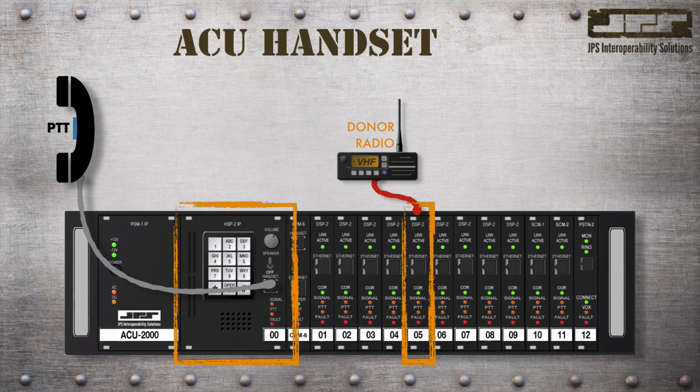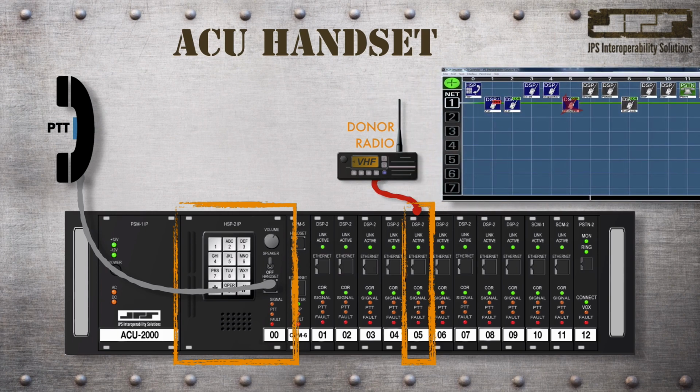At any time you experience communication issues associated with an interoperable cross-connection during actual operations, immediately disband the suspect interface from the interoperable cross-connection and then cross-connect the interface with the handset to conduct your troubleshooting activities. Do not under any circumstance begin troubleshooting with the suspect interface while in an interoperable cross-connection. By removing the suspect interface, you're allowing concurrent interoperability to continue and also allow subscriber units associated with the suspect interface to continue using your radios in an unimpaired manner in the field.